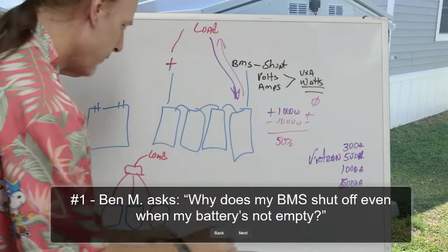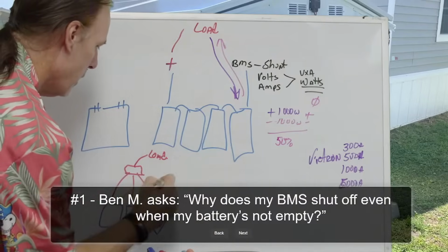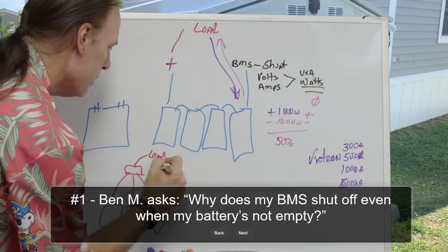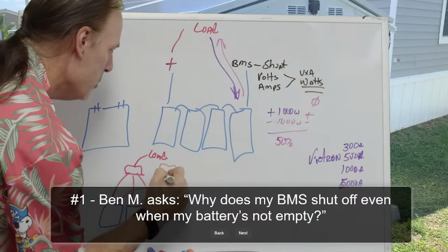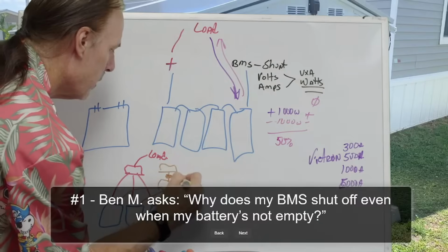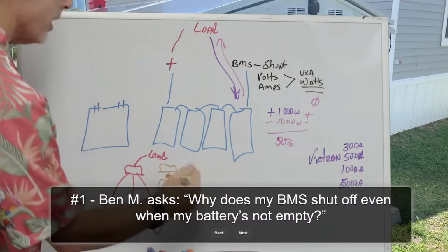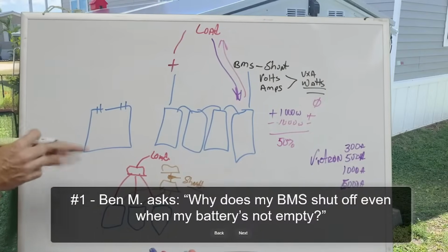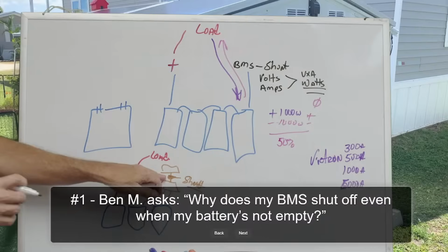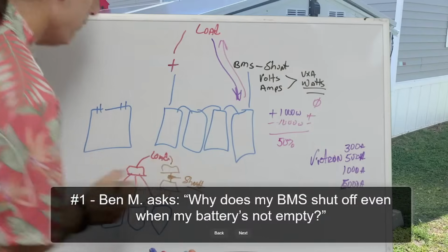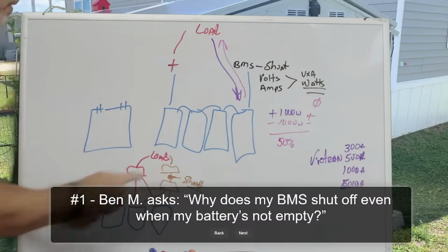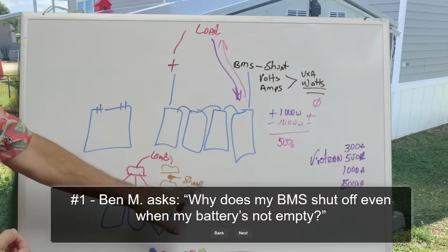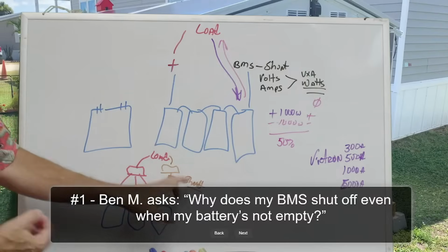And then on your negative bus, you run it through a shunt to a second bus and you put the shunt in right here. This would be a Victron shunt that has a much more precise calculation and measurement of the power, and then your load would run off of that. This shunt, being of higher quality and a lot more accurate, would give you a valid reading of what it is.